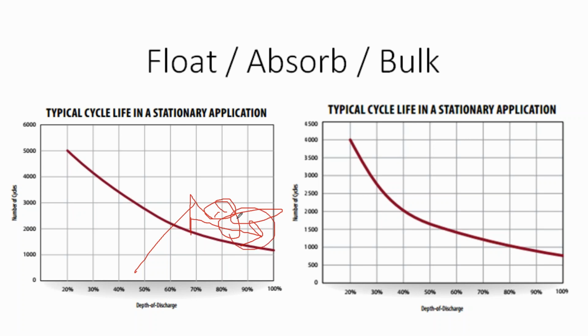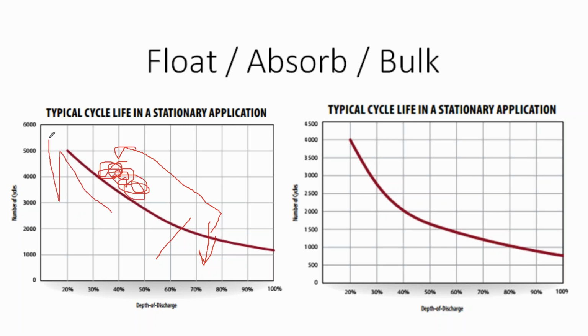And so when you hit this range, that's when the generator turns on. And so I might use a top shelf lead acid, and once my battery hits a 75% depth of discharge, that's when I'll click the generator and charge it back up to somewhere in here, and then I'll let solar take it away from there.